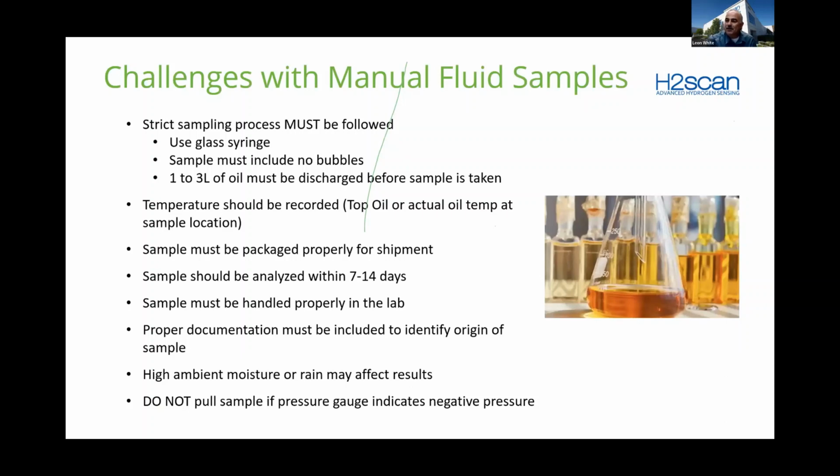So, challenges with manual fluid samples. For those that aren't on an IEEE or IEC committee, we typically call them oil samples, but as we're getting into various alternative fluids besides mineral oil, such as ester fluids, those are actually called fluids. So our terminology is changing, and I believe the best term to use today is fluid sample.